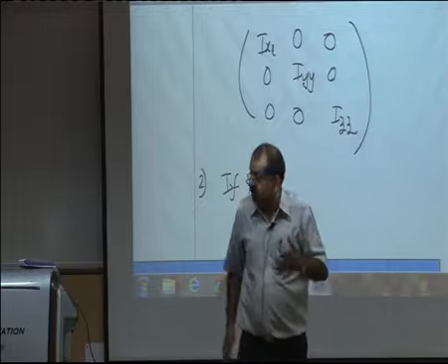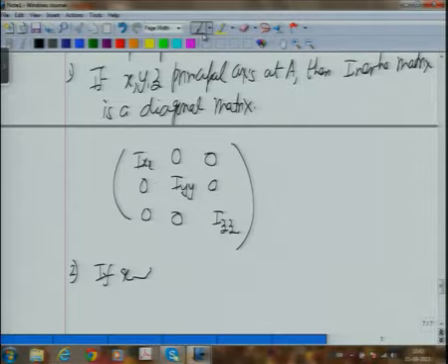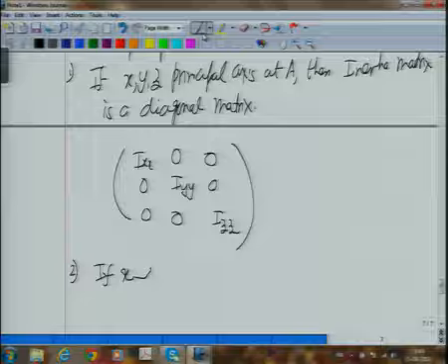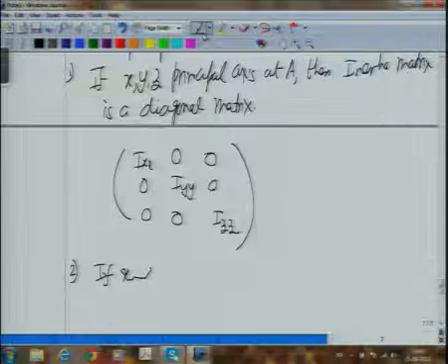We do not even have to look at it, because the plane of symmetry cuts the body into 2 parts, a left part, let us say, and a right part. If the x axis is perpendicular to that, when I am calculating the integral of xy dm, then for each x I will have 2 y's, a left and a right.